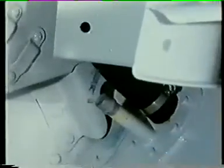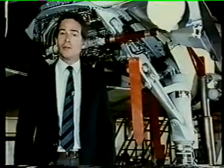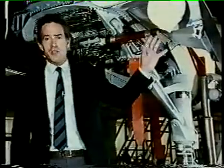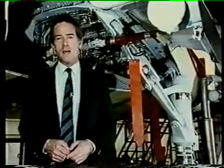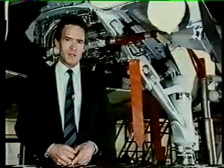Crevices which trap and hold water or other fluids must be avoided. Even so, some areas will still get wet or dirty. This could be due to water vapour condensing inside the aircraft or to the actual spillage of liquids in galley and toilet areas. So thorough protection, inside and out, is vital.